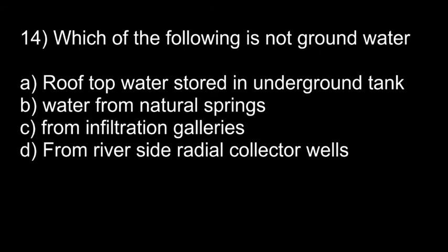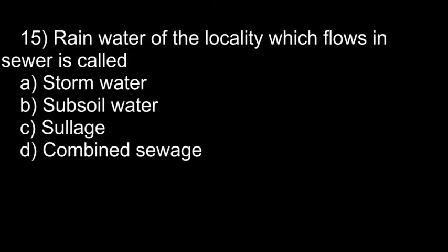Option C, infiltration. What are infiltration galleries? Infiltration galleries are horizontal tunnels constructed at shallow depths along the banks of rivers to intercept the groundwater table. These are most useful in the dry season. The quantity of water available from these depends upon the yield of source, that is, rate of water percolation, nature of soil, size of gallery, etc. So these are all about sources of water. So we can move to the next question.